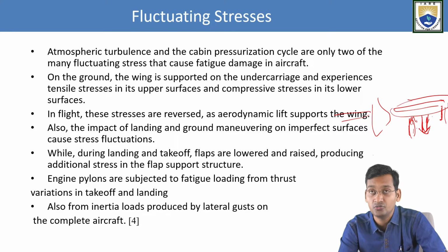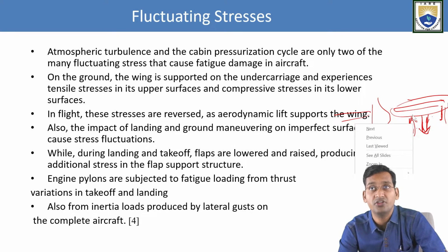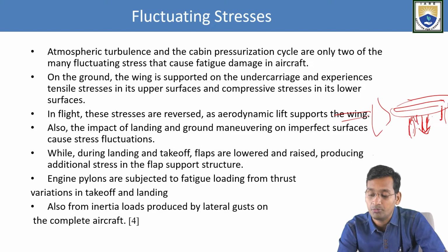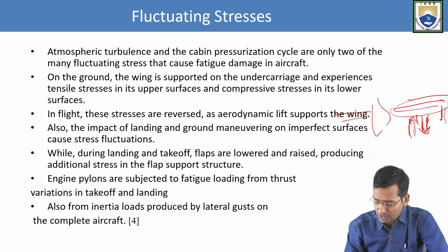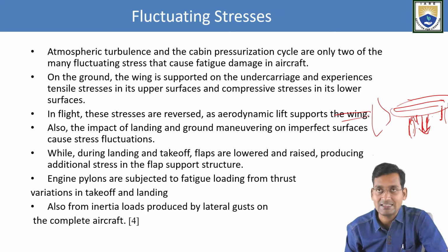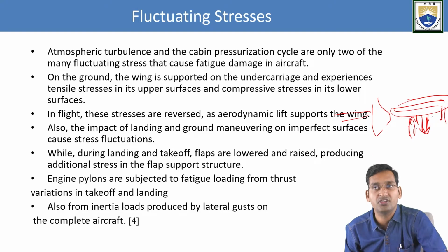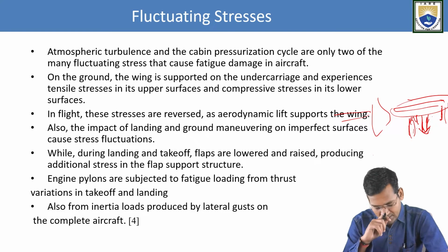So once we apply this force, then what happens? The upper surface has compressive stress, because we are pushing upward, right? And the lower surface is in tension, right? So the lower surface experiences tensile stress, and the upper surface experiences compressive stress.